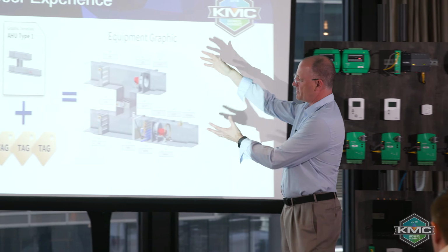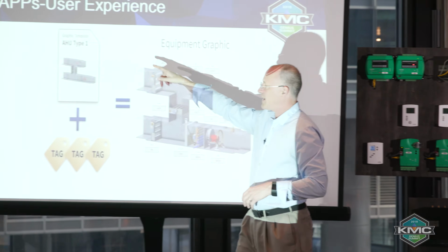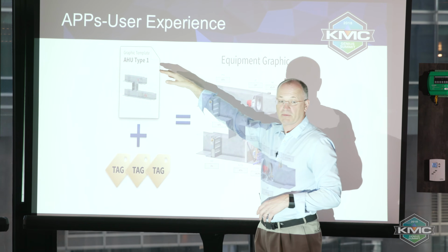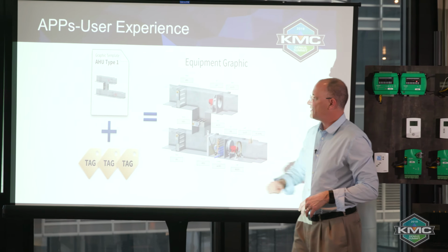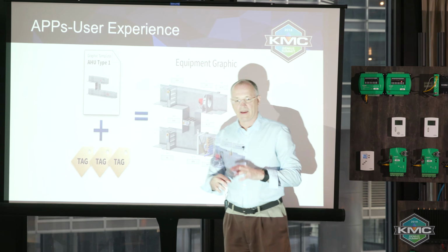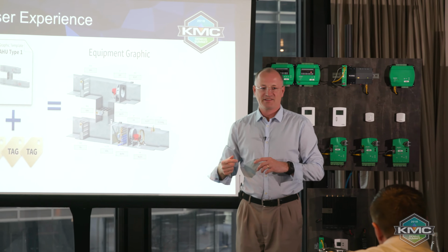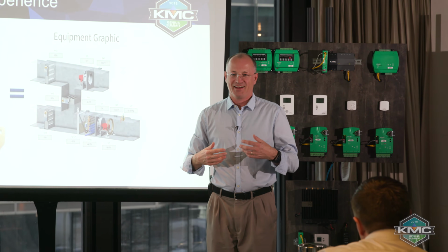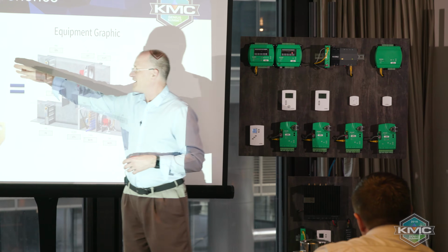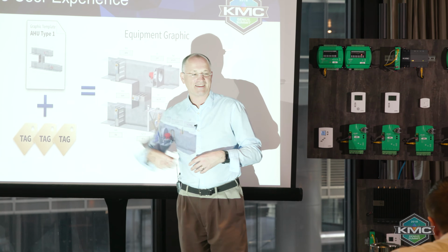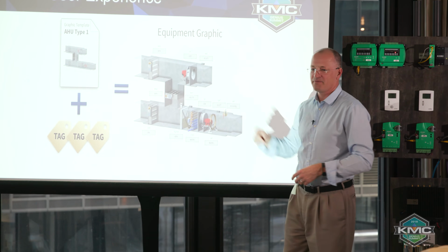So there it is. Instead of being a card, this might be a full-blown air handler. The idea is that we would have that one-to-many relationship potential as well. And so we'd have these tags on the graphic template. We'd have the tags down in our database on the points. And it's really like a matching game. Everybody gets into the room when I pull up this graphic, and if this template sees that there are matching set of tags for all the points, it automatically populates them here, here, and here.